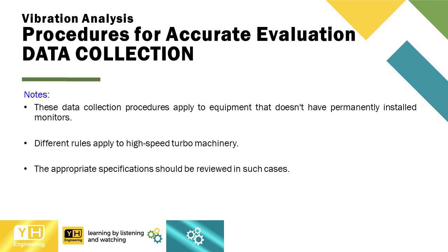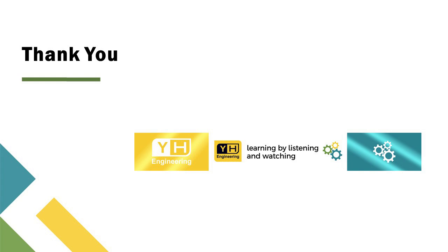Notes: these data collection procedures apply to equipment that doesn't have permanently installed monitors. Different rules apply to high-speed turbo machinery. The appropriate specifications should be reviewed in such cases.